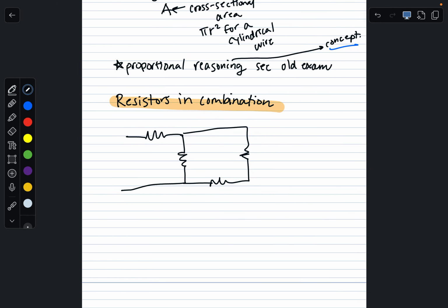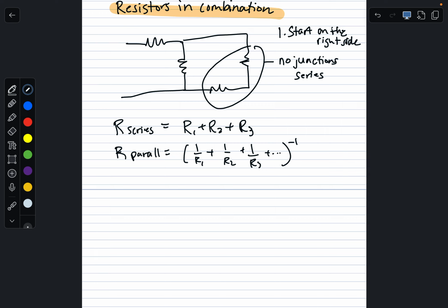And then those two will be replaced by one resistor. You can just pick either location to replace it. So let's draw the equivalent circuit with those two replaced. I'll put them both right there. So this is going to be R1 plus R2 right there. So I'm going to keep progressively combining them.